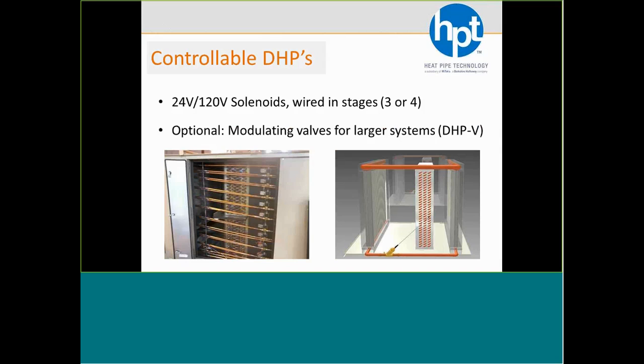So in this case, we've taken every 2 rows as its own circuit. So what you're seeing there is a 2-row wraparound heat pipe where you've got vertical tubes in this case being tied into common headers. Because the good thing is that allows us to use much fewer valves, and we're talking modulating valves now that can modulate that heat recovery versus just staging it.